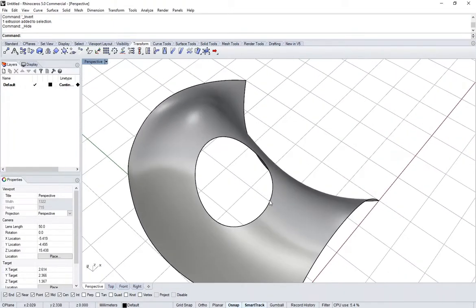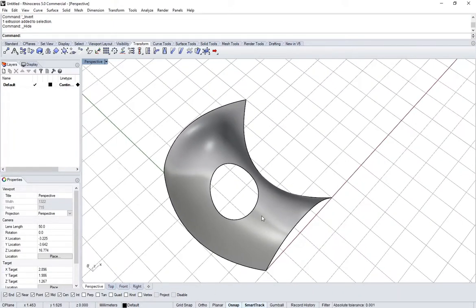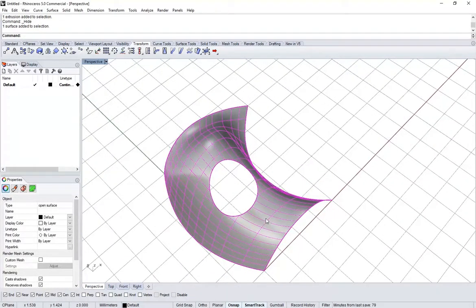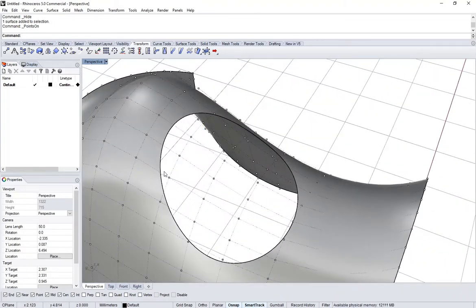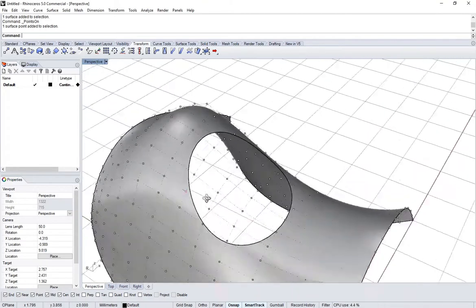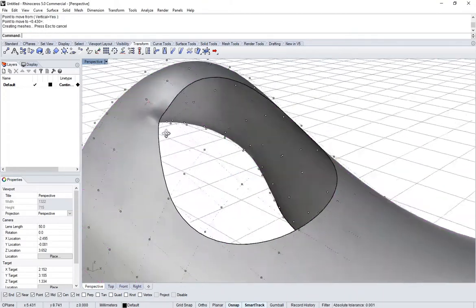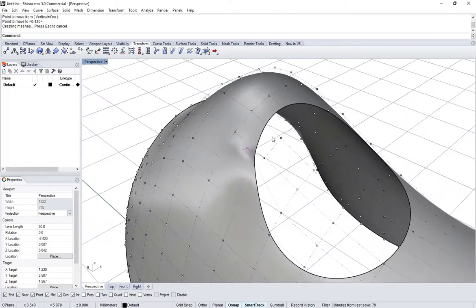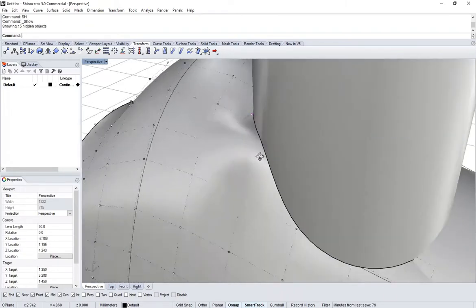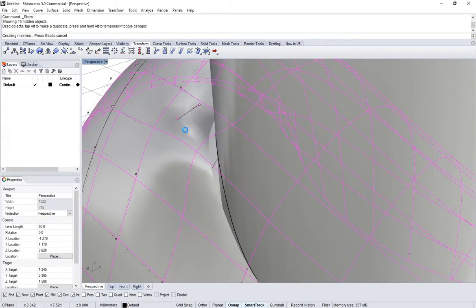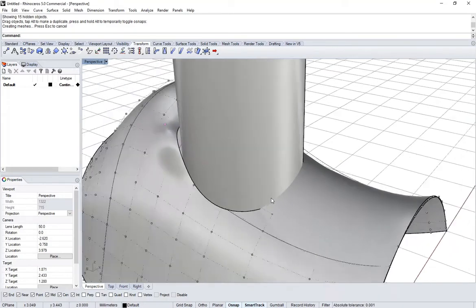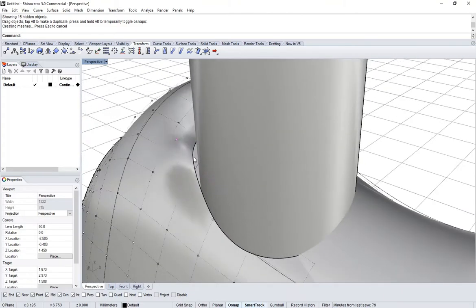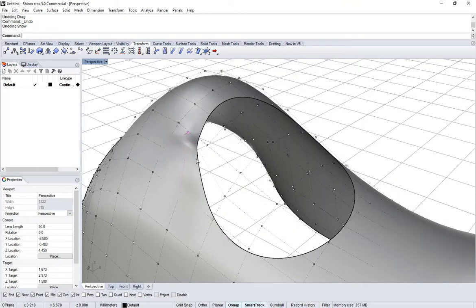Now it's important to remember that the split is just an operation that's sitting on top of the base surface geometry. So if we select this geometry and hit F10, we see all the same control points still. There's nothing about that split reflected in the control points. And in fact, if we start to edit these control points, it's going to try to figure out how to redo that split operation, but it will not necessarily line up with the original cylinder. So you have to be careful when you're starting to affect the boundary of the surface with things like splits. You can lose some of the editing functionality of the original surface.